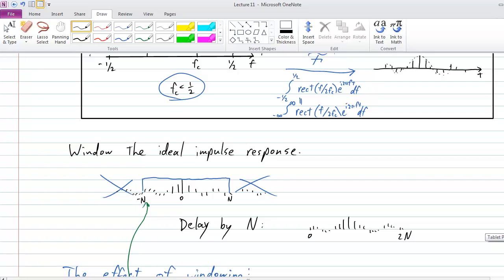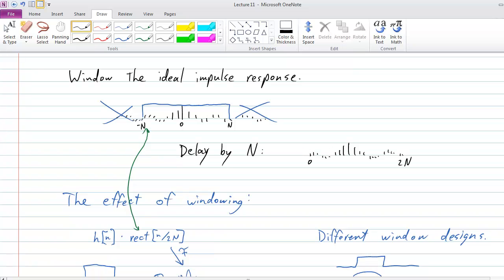We have some circuit board that is taking samples of a signal. What do we do to implement a FIR filter? Yeah. Exactly. So let's say, first of all, that we have to store the last 2n samples.